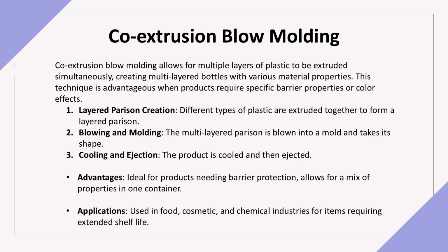Co-extrusion blow molding allows for creating multi-layered bottles. Layered parison creation. Different plastics are extruded together. Blowing and molding. The multi-layered parison is blown to fill the mold. Cooling and ejection. The product solidifies before ejection. Applications include containers requiring barrier properties, like food and chemical packaging.